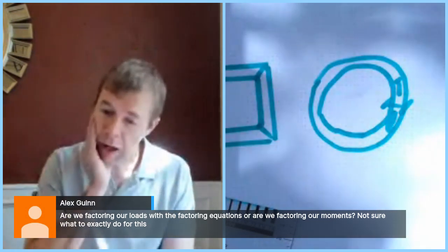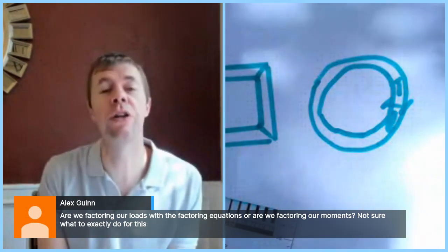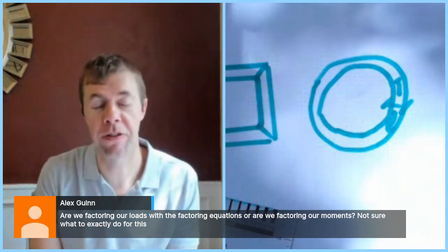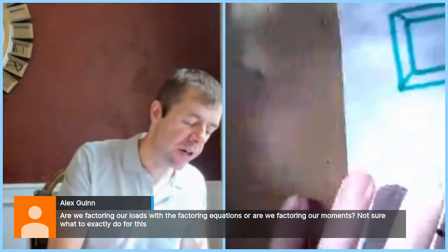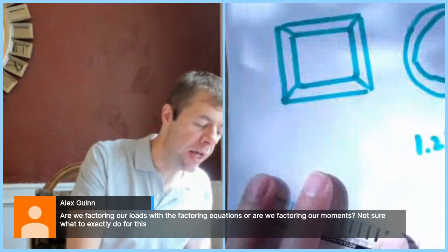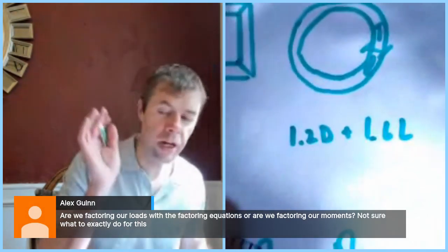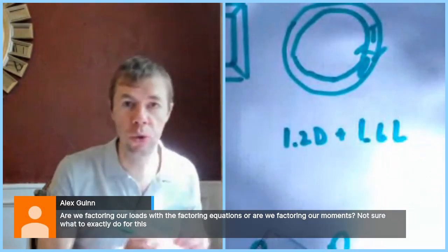So Alex asked about, are we factoring our loads or are we factoring our moments? So Alex, I will tell you, you can do whichever one makes most sense to you. One benefit sometimes to factoring moments. What Alex is asking about is there are load factors that we have, at least on LRFD type designs, of 1.2 dead plus 1.6 live. And there's wind, there's whatever. Alex wants to know, do I factor my loads or do I factor my moments?